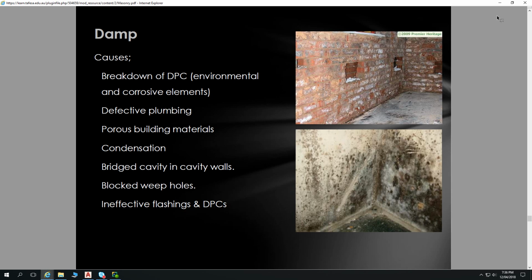Although, talking about progress payments earlier, I also did a final progress payment on a house that when I went to look at it, they hadn't put damp-proof course all the way around. There was a section in a wall where it was missing. I don't know whether they ran out and then just decided to keep building or what. Super cheap stuff. Why you'd not do it, don't know, but that's a significant issue to rectify.